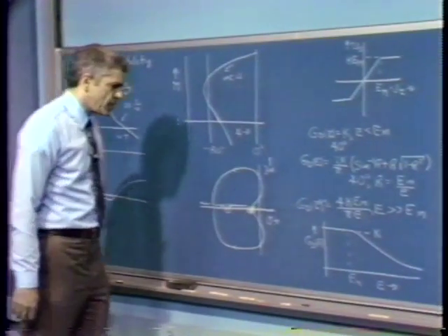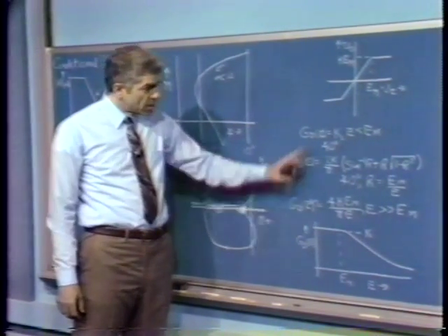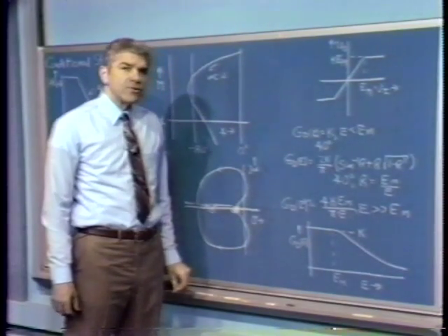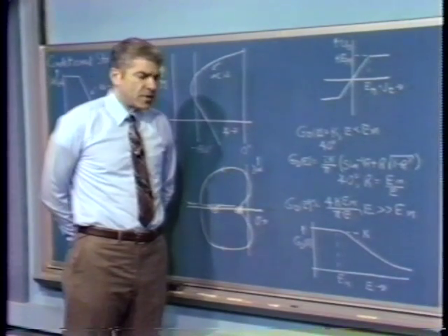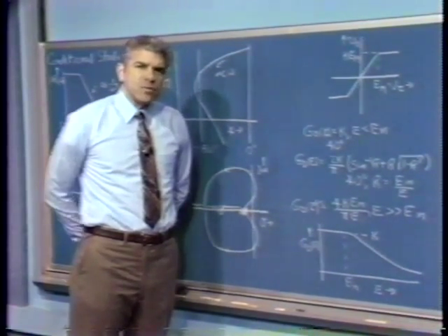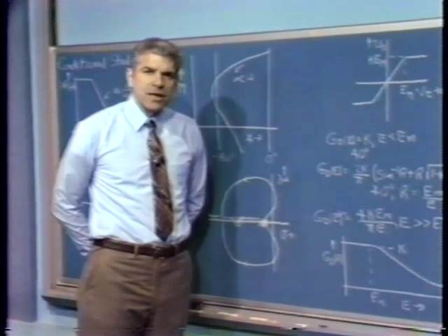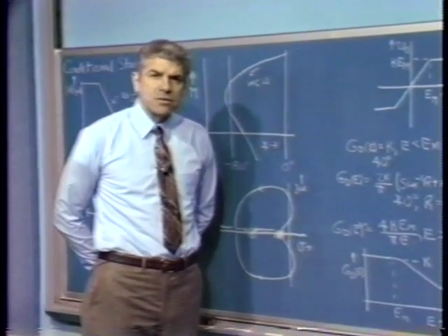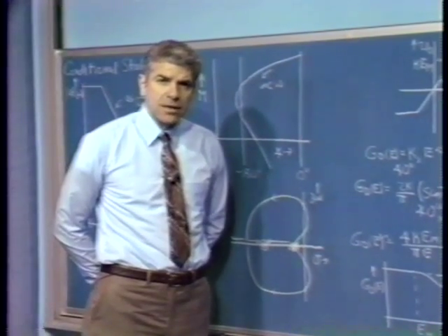Now we can see the difficulty. Suppose we have a system that includes this sort of a nonlinearity with this kind of a describing function. If we then analyze our system by describing functions, well, let's see, what are we really doing? We're effectively linearizing the system in a particular kind of a way. Describing function analysis really amounts to a linearization about an operating point that's described by the amplitude of the signal applied to the nonlinearity.